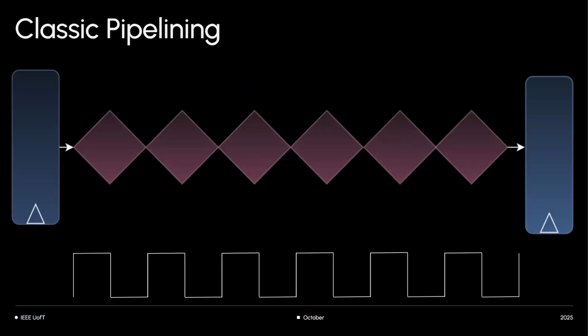It's just an oscillator. It's like 1 0 1 0 1 0. That's a clock in a digital circuit. The edge runs from a low voltage level to a high voltage level, and that edge is just a rising edge, and the other is a falling edge. In a typical pipeline like this, these are flip-flops. They'll only latch in data. When I say latch in, they'll only register the data on an edge. Does that make sense? Okay, so we will be simulating the edge through clicks, all right?